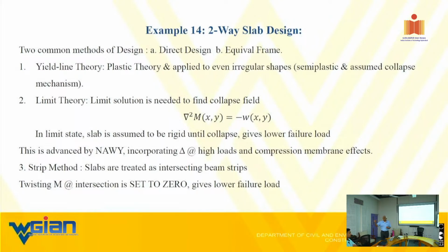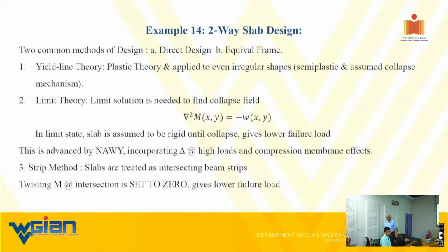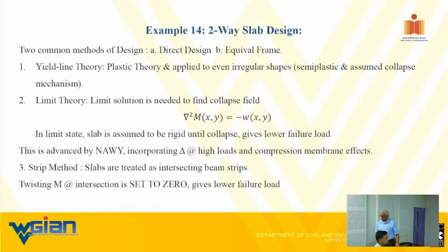What you should be asking me is, I'm designing a steel reinforced concrete beam as an under reinforced beam, because the concrete strength keeps increasing for 10, 15, 20 years, then would it become an over reinforced concrete beam? If we don't consider this degradation or increase in strength, suppose the strength is static, at any duration we are testing the beam. It is not about decrease or increase in strength. I am just asking that if you test an over reinforced beam, we will not be able to get the property of the FRP bar.